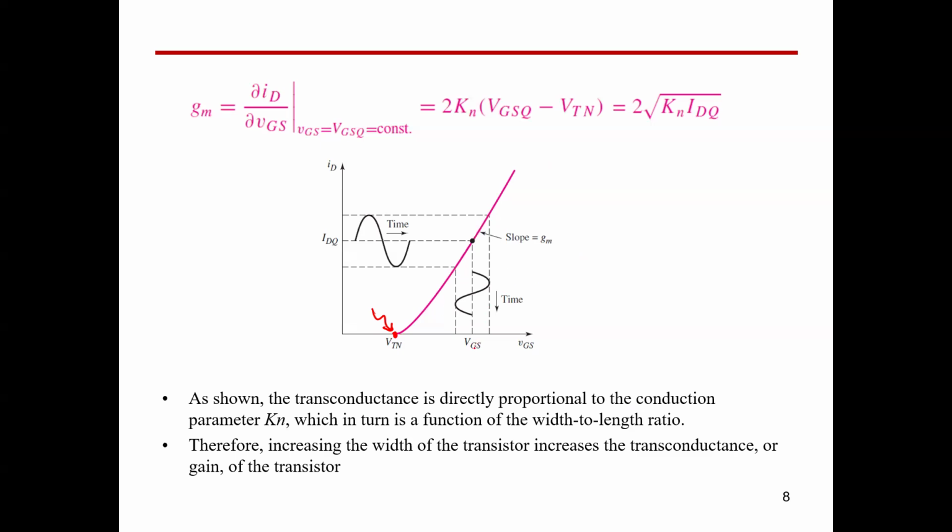If this is the input signal here through VGS, this is going to be the current, and this means the slope of this curve is representing our transconductance. So this is the value of GM at the operating point, okay? So this is the complete curve of GM, which is partial ID by partial VGS, and the operating point here at the certain value of VGS and IDQ, or the Q point, is nothing but the value of transconductance that we have right here. Okay.